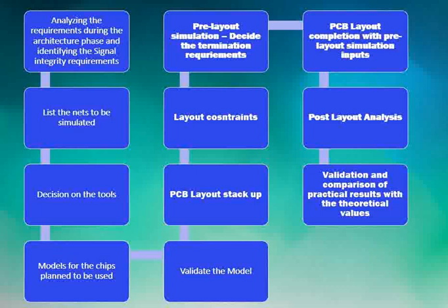So this is where a PCB is not ready, a schematic is not ready, but the signal integrity engineer starts getting involved and getting the inputs from the design engineer, and gathering all the simulation related requirements. And this is the phase where he does a pre-layout simulation.